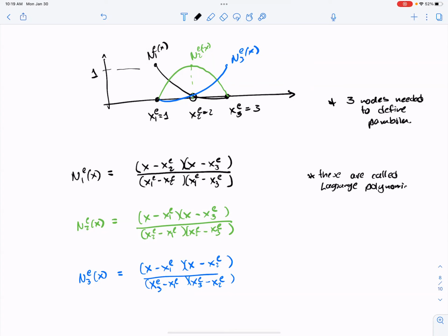Now, what is a good degree of elements to use? Honestly, linear or quadratic, because of a couple of reasons. One is, even when you use quadratic, they are flexible enough to have a good interpolation of functions. And the other one is that for Lagrange polynomials, for quadratic, you don't see the effect. But if you add more and more terms, I don't know if you do any Lagrange polynomials in any of your classes? If you do more and more terms, then you start having a lot of oscillations.